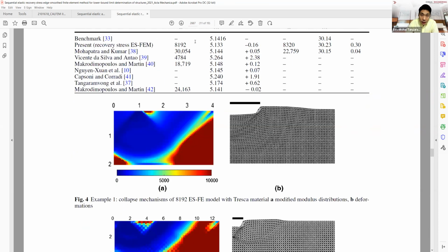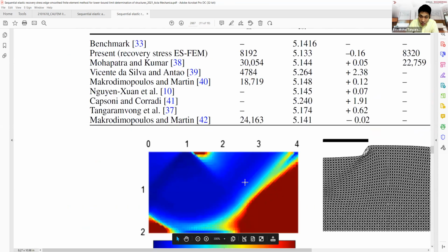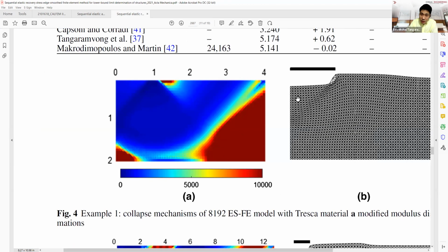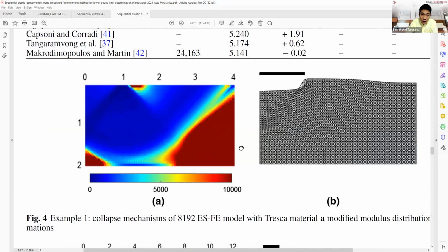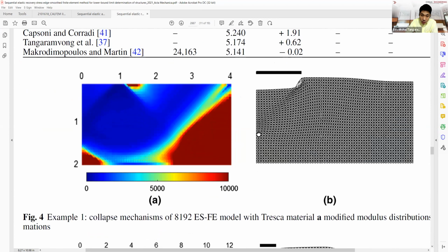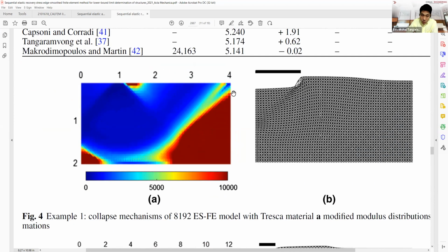If you do the uniform mesh, the way I subdivide the element is like you just draw the grid line, and the size of the grid line is so small. To get the accuracy, of course, we have the benchmark to compare, and we plot the convergence curve as well, as I showed you before.